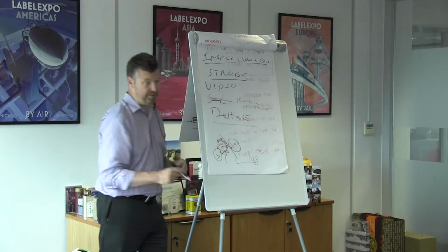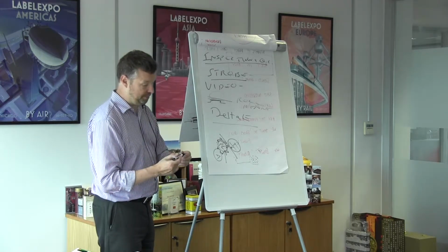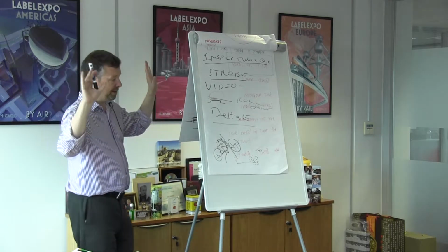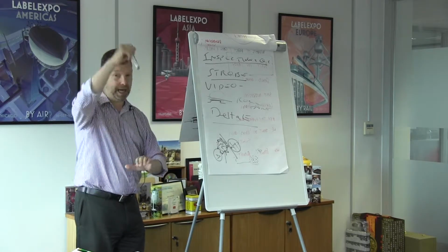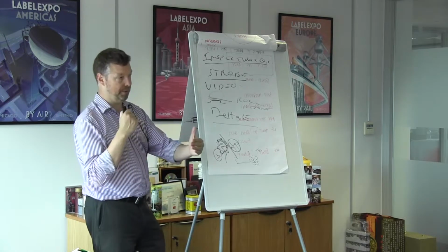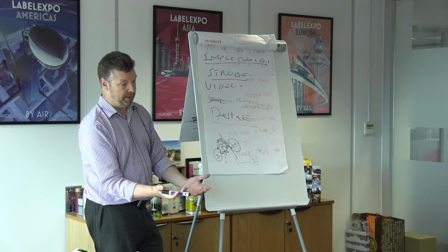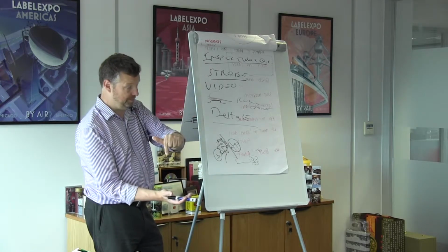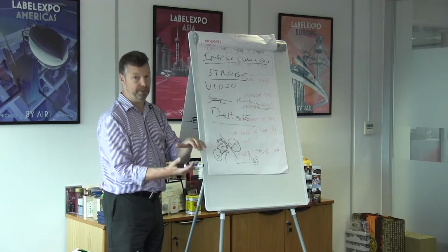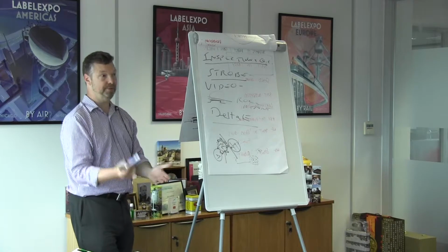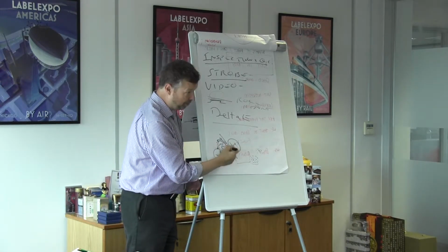So what it means now is that that operator does not anymore have to go up and down the machine. So now you can see a make ready of a flexo press. It's fully automatic, hands off. Okay, so things start to print, go slowly. The traditional camera is looking for any print problems, hickeys or splashing of the ink or whatever. The other camera is looking at the color, and another camera is looking at the registration marks, and another camera is looking at the printing pressure. And it's all being fed back through the press to all the motors that control all the cylinders on the press.